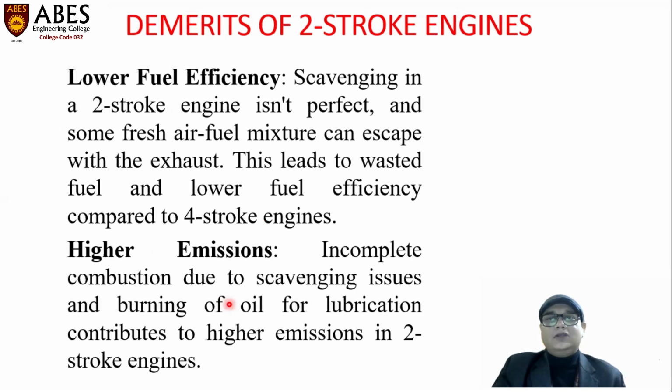As far as the demerits of the two-stroke are concerned, it has lower fuel efficiency. Scavenging in a two-stroke engine isn't perfect, and some fresh air-fuel mixture can escape with the exhaust. This leads to wasted fuel and lower fuel efficiency compared to a four-stroke. Next is higher emissions. Incomplete combustion due to scavenging issues and burning of oil for lubrication contribute to higher emissions in the two-stroke engine.